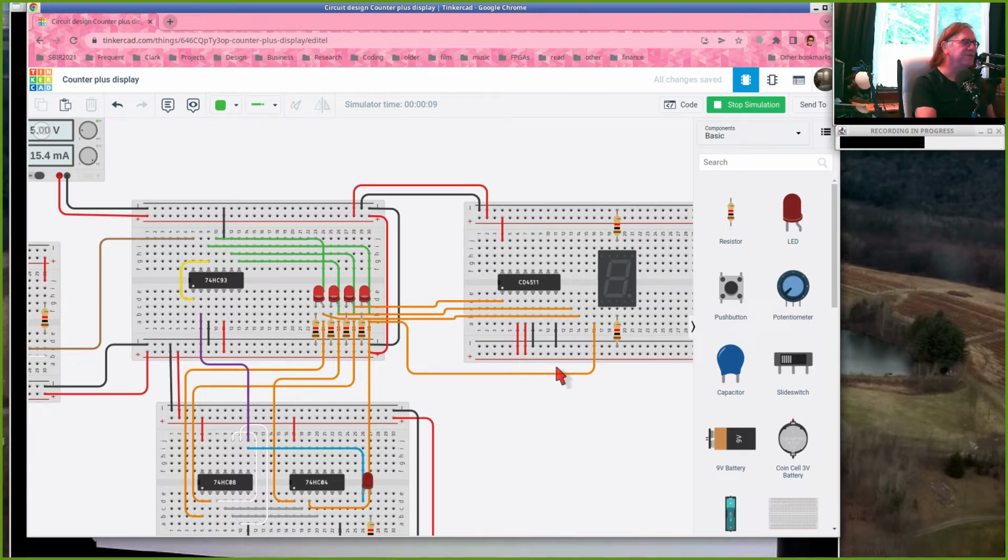So here I've disabled my reset circuit and I've disabled the display, but when I get to the point where the counter should roll over, my simulation time almost freezes. It slows down considerably, right? This should be real time, and it's doing so much calculation it can't keep up, so we're seeing a millisecond pass every 2 or 3 or 4 seconds of wall time. And this is a problem in the simulator.